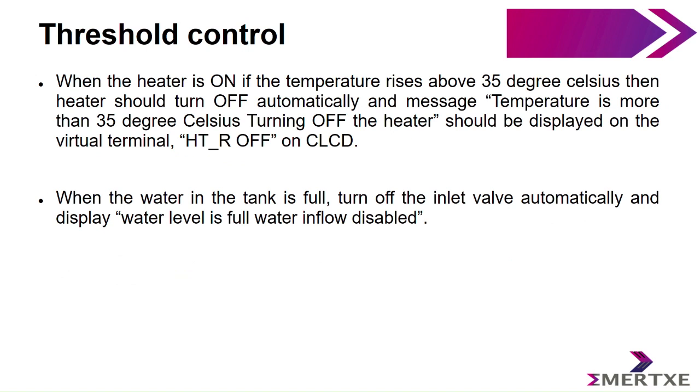What is threshold control? When the heater is on, if the temperature rises above 35 degrees Celsius, then the heater should turn off automatically and a message like temperature is more than 35 degrees Celsius, turning off the heater should be displayed on the virtual terminal, and HT_R off on the CLCD. When the water tank is full, turn off the inlet valve automatically and display water level is full, water inflow disabled.